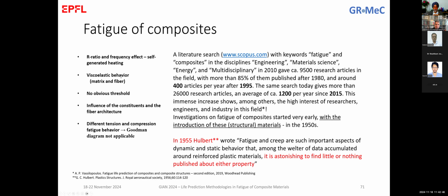These articles discuss the effects of the R ratio, frequency, so the loading, on the fatigue of composites. They are investigating viscoelastic behavior of the materials. They investigate the influence of the constituents and the fiber architecture, so the way that we create the materials. They talk about the differences between the loading patterns. If we are in tension or in compression, the fatigue behavior is much different.